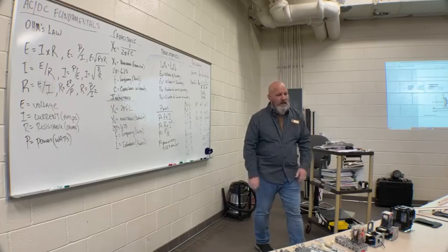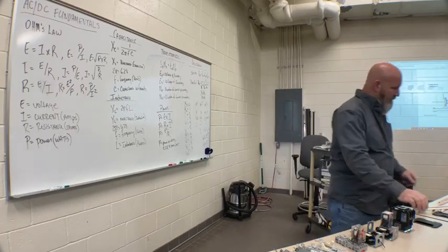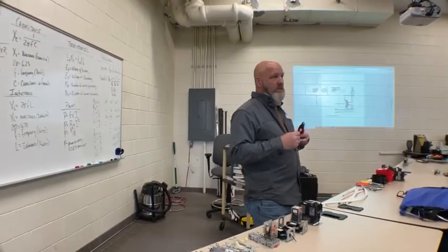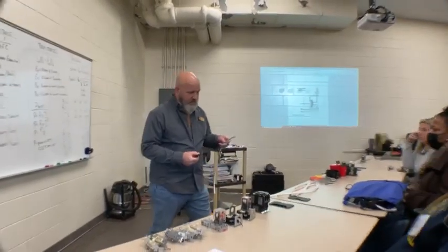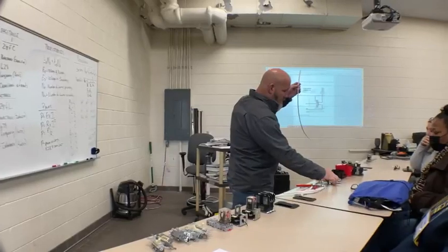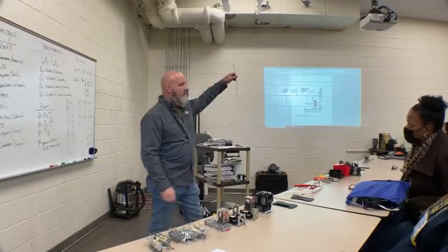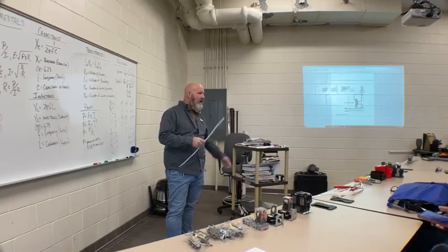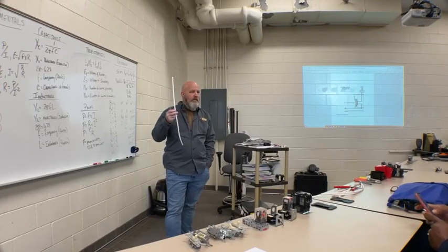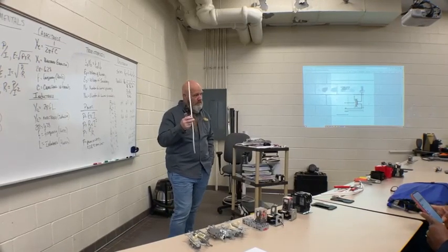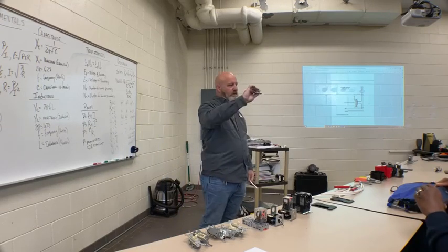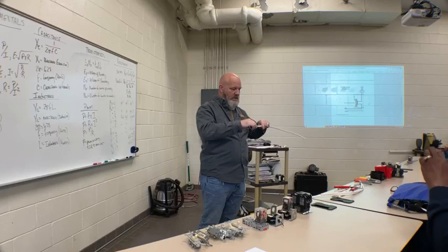But today, I want everybody to get a piece of wire. Has anybody here not stripped wire in your previous classes? Okay. So this is what we call Romex. Romex is the trade name. The code name is NMB, which is non-metallic building cable. And we strip it with a Romex stripper, or we strip the outer sheath.